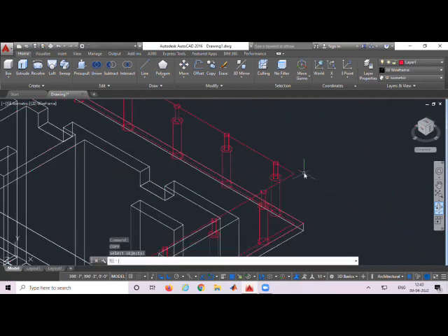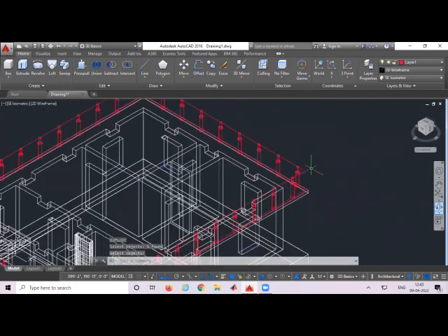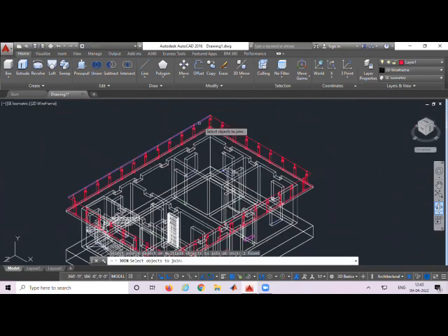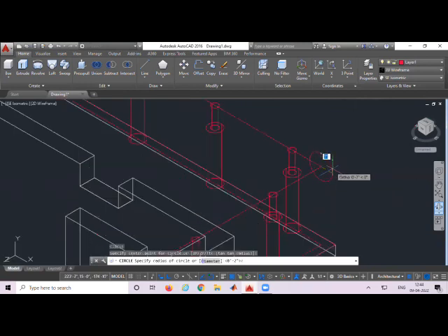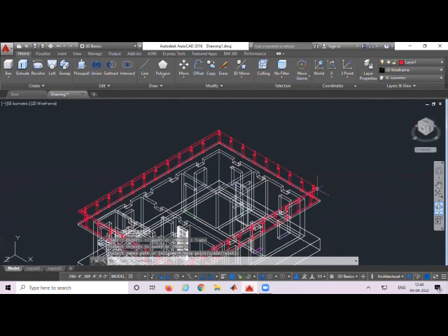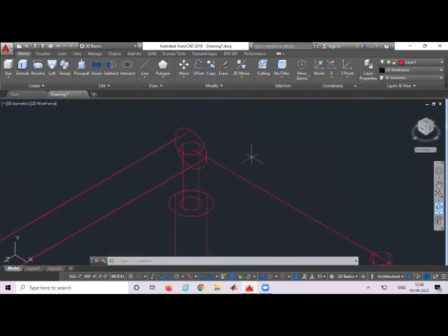If we select any one place over this line, it selects the total object, so that has to be exploded. X enter, select the rectangle. Now it is converted into individual lines, as you can see. Next, select 3 of the lines and join them. J enter, 3 of the lines selected, enter. Now they are all converted into a joined line. Next, C enter, 4 inches enter as the thickness of the ballast bottom. What we provided as the thickness of the ballast bottom, 4 inches, is also provided for the railing. So 4 inches of the railing is created.